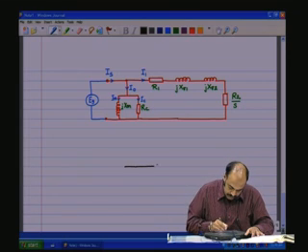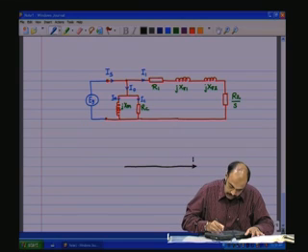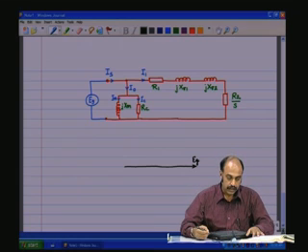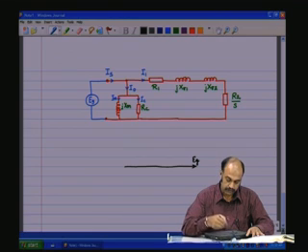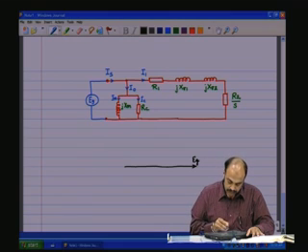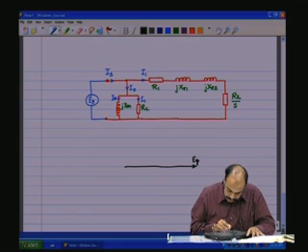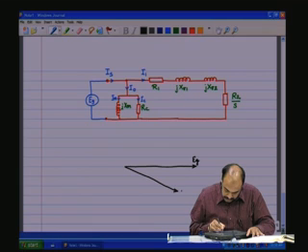We will draw EG. This is EG. So we start with the phasor EG. Now lagging EG are all the currents, because they are all inductive in reactance. And this IS is also going to lag EG. So let us say this is IS.